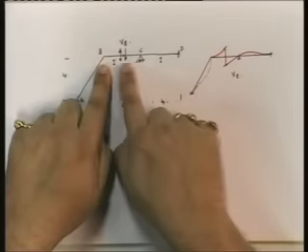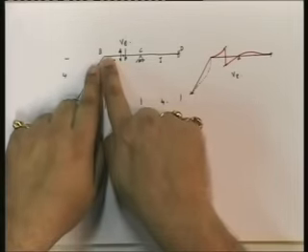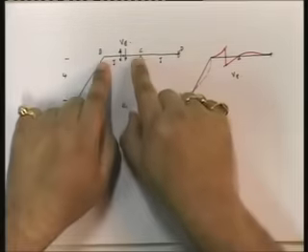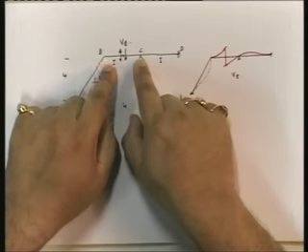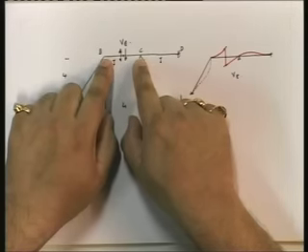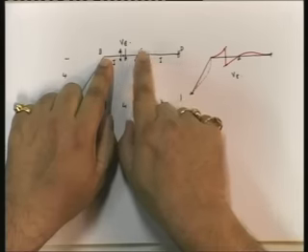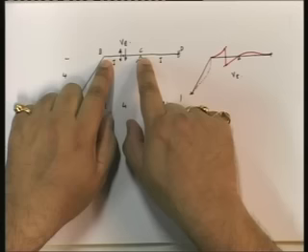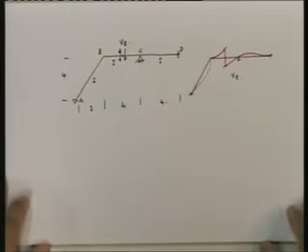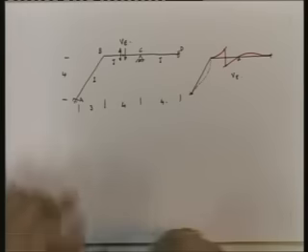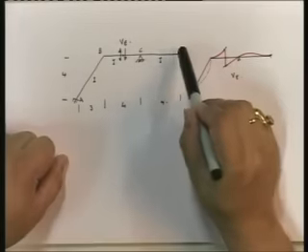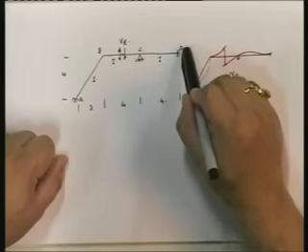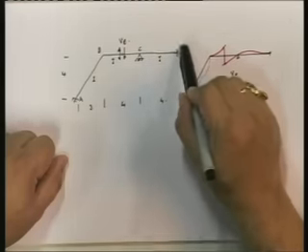Now, as the load proceeds from B to C to D, let us see, when the load is between B and C, you set up a fixed end moment at BC and CB, and then when you go from C to D, you set up a bending moment at C and D. So therefore we have to tackle three problems. DC we are not going to tackle because it's a fixed end, and the fixed end moment DC is going to land up being there.